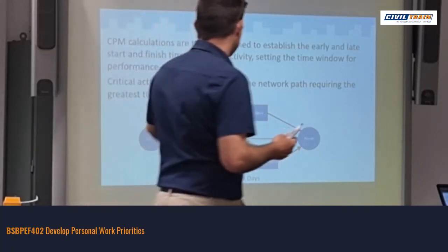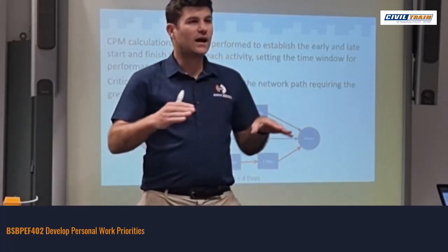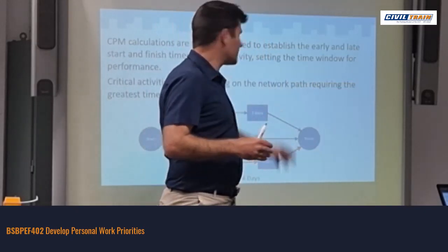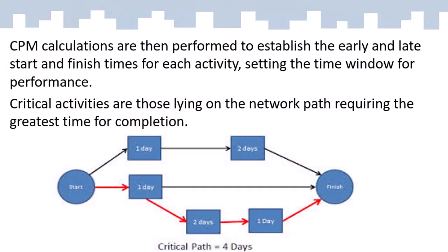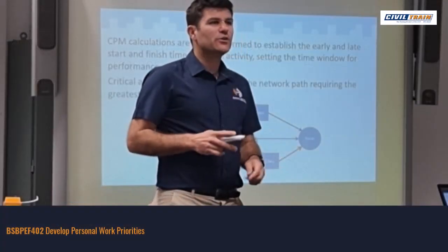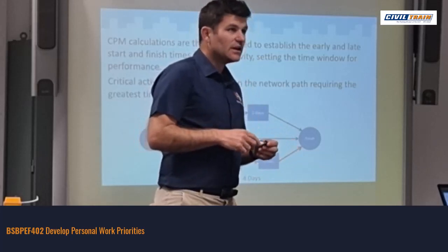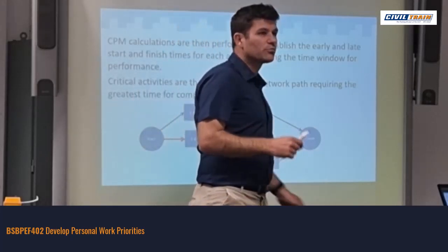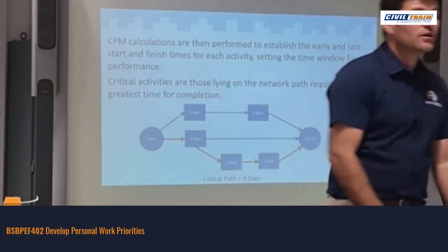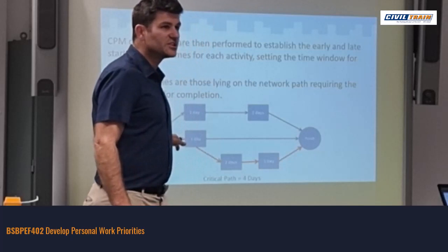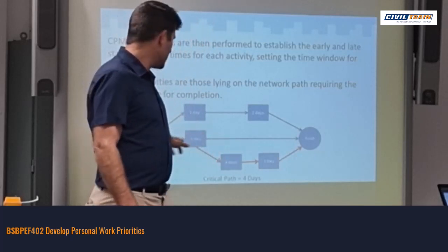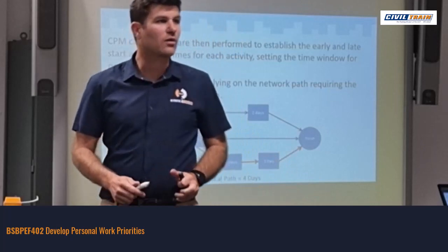So if I had a work team on this and a work team here, technically I could start by 3 days. I've got a day up my sleeve theoretically in that planning. So when we work out the critical path, we're basically working out the longest duration of the actual project. Now, it depends on how your work schedules are calculated. If it's been budgeted that your program is done on critical path, this is again a perfect world scenario on planning. That means within those 4 days, nothing goes wrong.